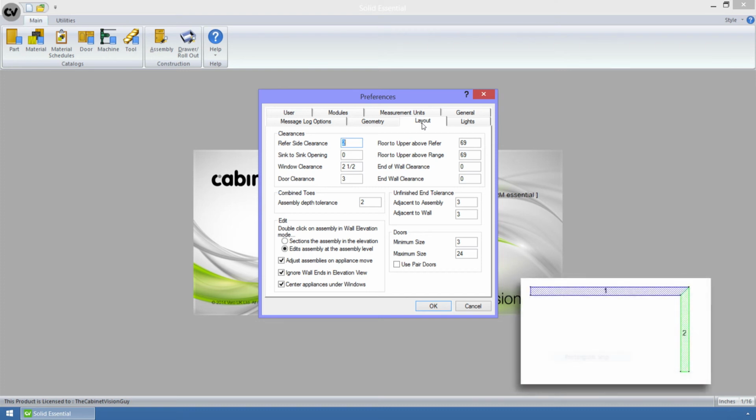The end of a wall is just that, the end of a wall, while a wall end is a special wall type. When you make the wall, you can just specify that it's supposed to be a wall end. The difference between a wall end like this one and any objects that are next to the wall end is what end wall clearance means.